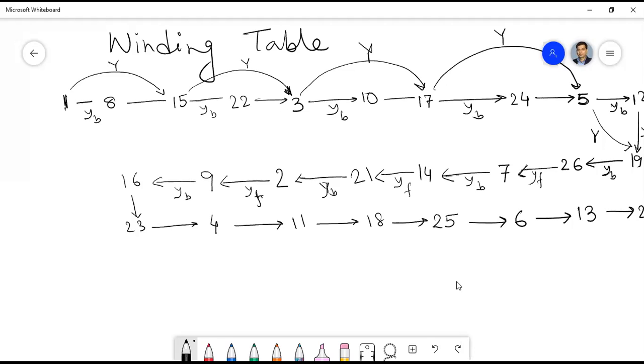This circulating current will not only flow through the coil and heat up the armature, but also flow through the brush, and it will create some commutation problem and also sparking at the brush contacts.